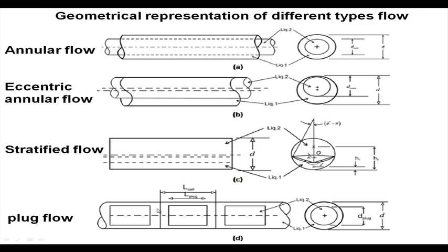Now, since we were trying to confine our attention to low to moderate velocities, naturally this analysis has been developed for the plug flow pattern, where we have neglected the nose region of the liquid plugs and assumed rectangular liquid plugs, in this case organic plugs, since water is the wetting phase. Organic plugs traverse through the continuous water medium, and there are water slugs in between the toluene slugs, and there is also a water film encircling the toluene slugs.